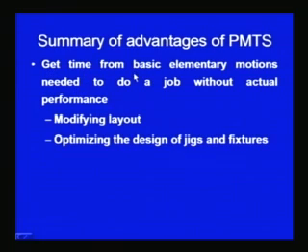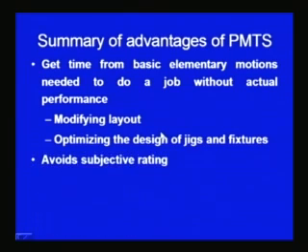It helps to get the time from basic elementary motions to do the job without actually performing it, which in turn helps to modify the layout and optimize the design of the jigs and fixtures, so that the time required for carrying out the job can be reduced. It avoids the subjective rating which is normally associated with work sampling and time study. In this case the subjective rating is not a part of the PMTS system, and it is not decided by the judgment of the time study man or the work study man.